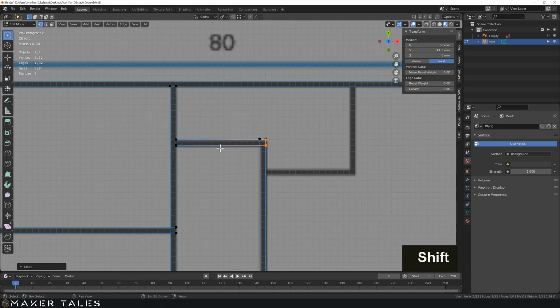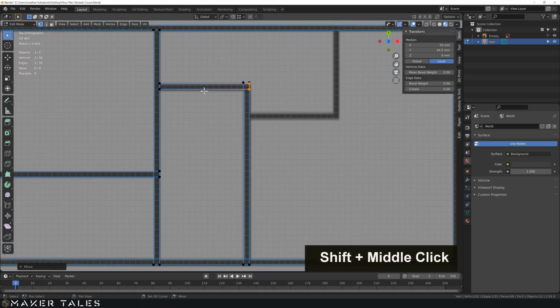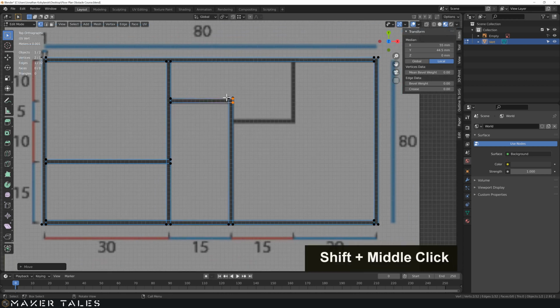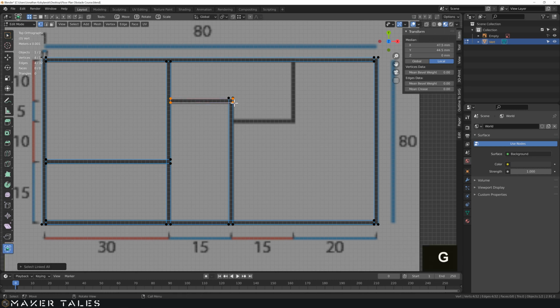So with that there, let's double check what's happening. So we know that this is the bottom, so let's select all of this with Control L. Let's use CAD transforms to make sure we're getting some precision. We're going from this vertex all the way down to there, which is correct. So I'm going to constrain this on the Y, going to this vertex here, which is 30.